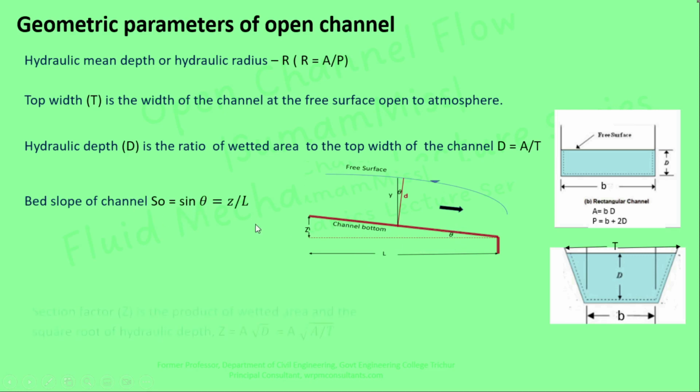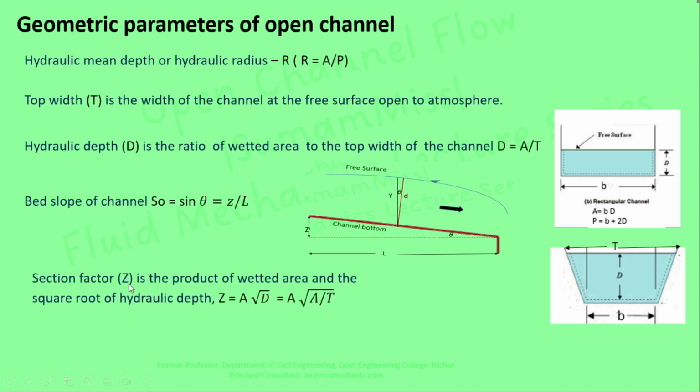The next geometric parameter is the section factor. It is denoted by Z. It is a product of wetted area and the square root of hydraulic depth. So hydraulic depth is equal to A by T. So Z is equal to A into root of D, or that is equal to A into root of A by T. So in open channel, different shapes are possible, so one should know about different geometric elements and geometric parameters for solving the problems.